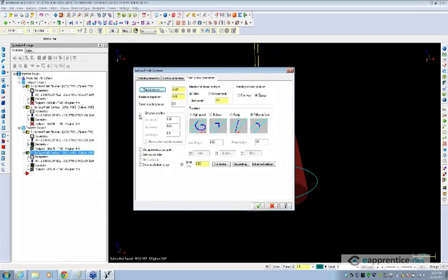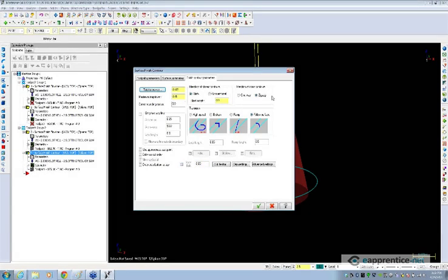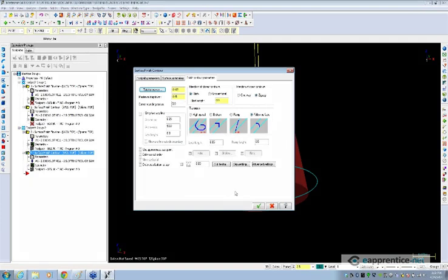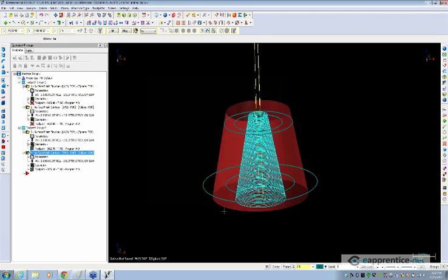And I don't think it'll allow you to enable that. Definitely not with the spiral entry. I know there's another option that we have to set to be able to turn on the entry and exit line. But yes, we can use the entry and exit arc and line motion to support lead in and lead out for Surface Finish Contour. And we'll look at that on our next part.